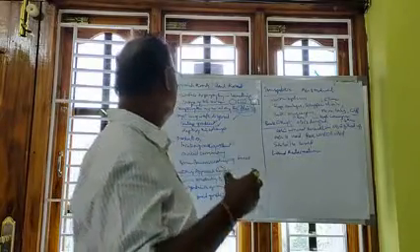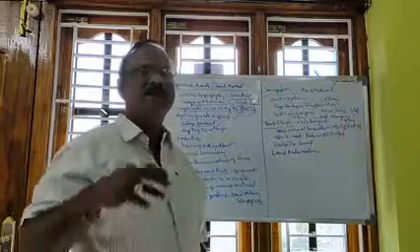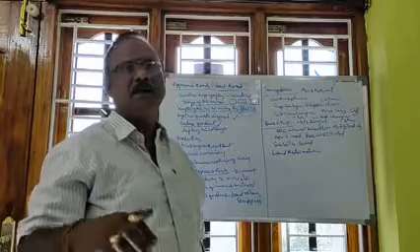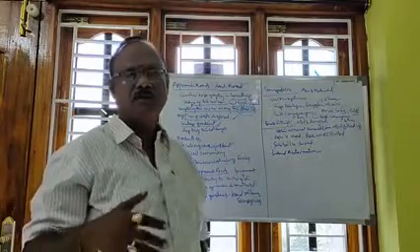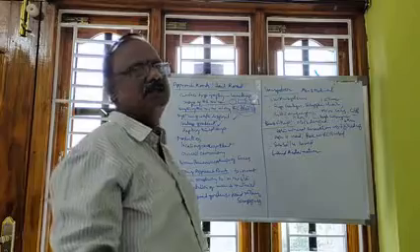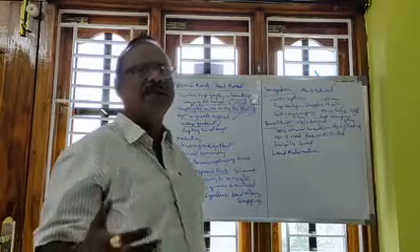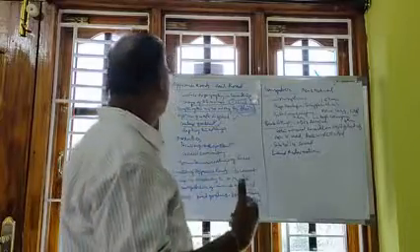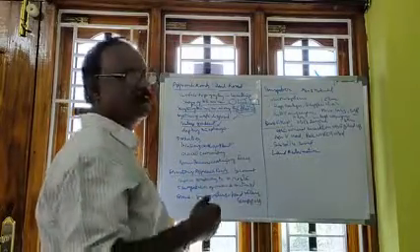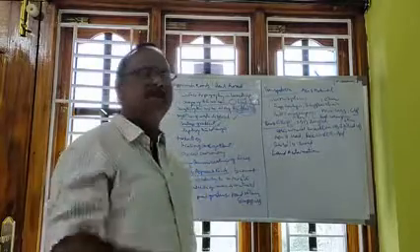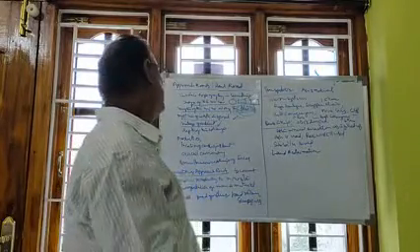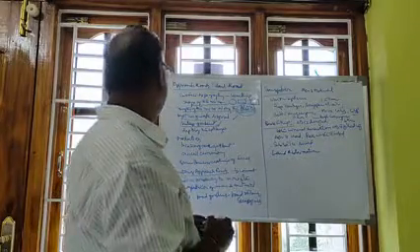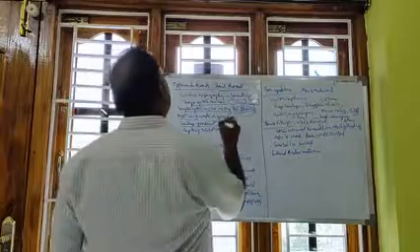So this is the haul gradient. If the gradient is very high, little machinery is used. Very high means not 1 in 5, not 1 in 6, not 1 in 4. These are not used at all. Gradients of 1 in 8, 1 in 9 are used. But in heavy mechanization, where we use heavy machinery, the gradients must be less than 1 in 10, that is, lesser gradients: 1 in 10, 1 in 11, 1 in 12.